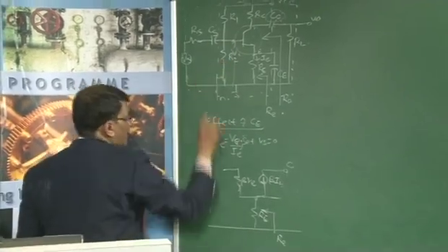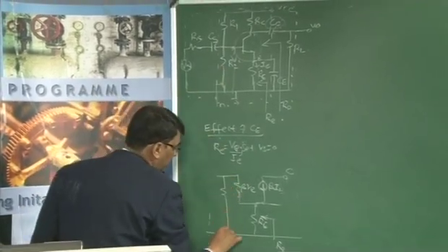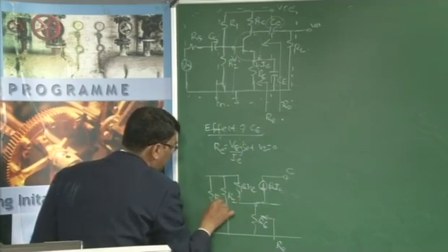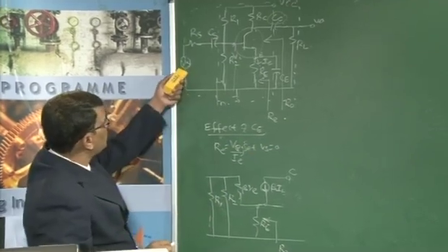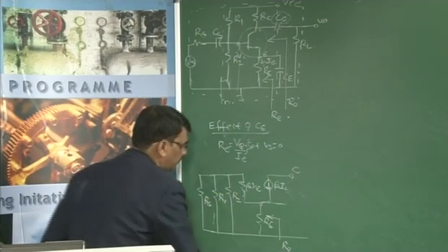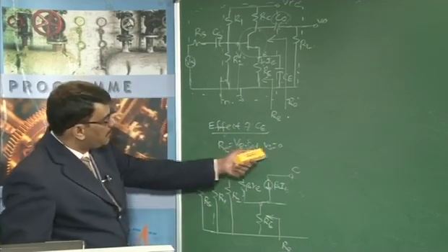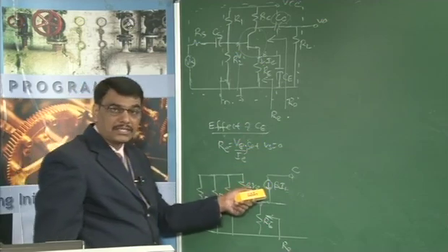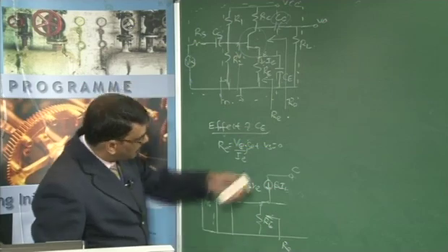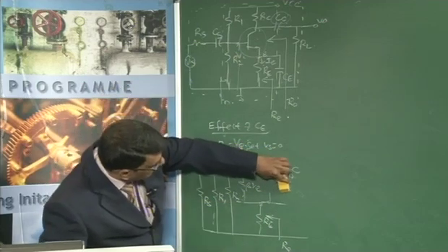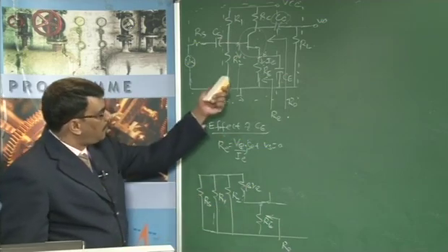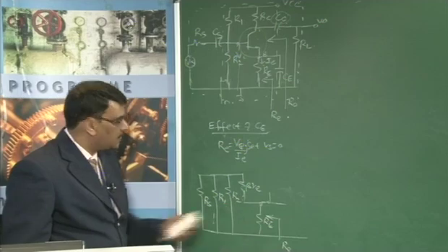From this base, this R1, because you have to set V_CC equal to 0, R2 is in parallel with R1. Then Vs equal to 0 acts as a short circuit, so this Rs is also connected in parallel. When Vs is equal to 0, the constant current source I_B is also 0, and this constant current source acts as an open circuit. Then the equivalent circuit of the amplifier to determine R_E is shown in this figure.